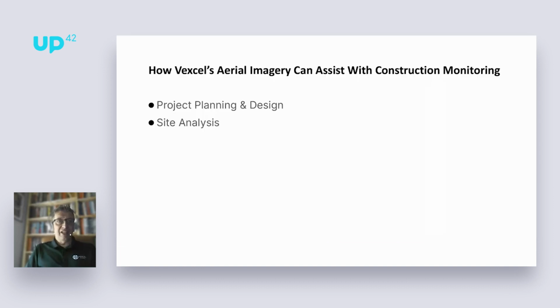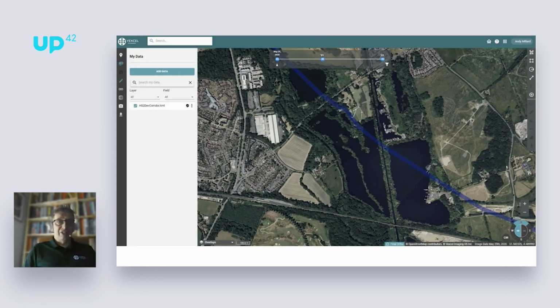We can then do site analysis. The aerial imagery can be used to analyse the topography, vegetation cover, other physical characteristics of the site. This information is crucial for understanding the feasibility and potential environmental impacts of a development project. It can help identify potential challenges and inform decisions regarding grading, drainage and landscaping.